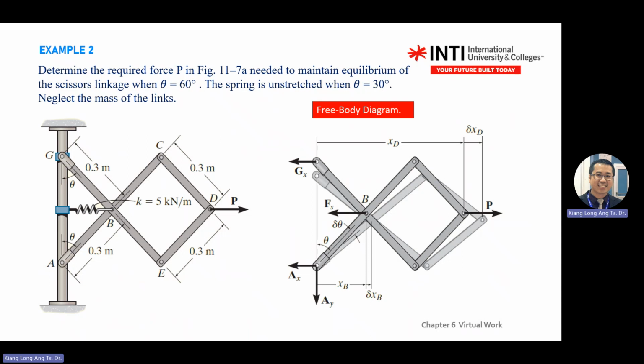So you can develop a system where you look at the forces first. Look at the forces where any point is moving in a straight line, move up, move down. After that, then only you go to the angle. Then you see whether any member has a change of angle. So point P will move to the right at a distance of delta xt.